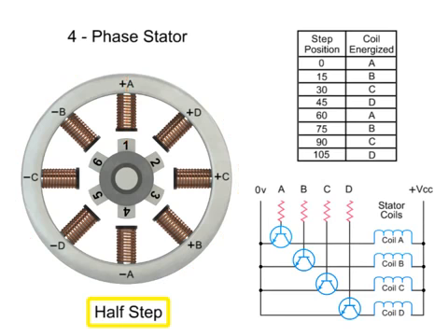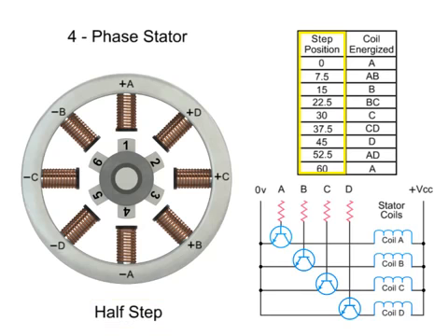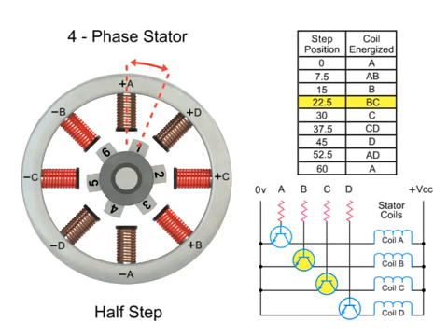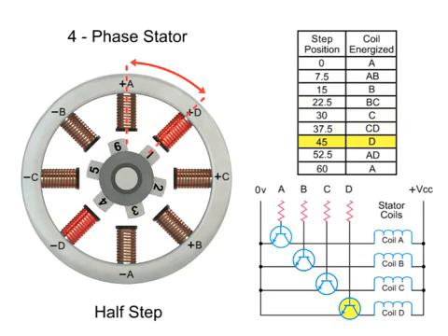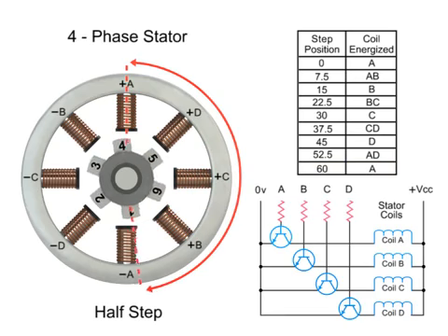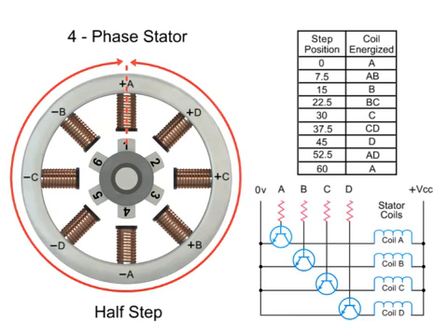For half-step mode, the stepper motor's resolution can be doubled by altering the switching of coils. Half-stepping occurs when one winding is energized and then 2 windings are energized alternately, causing the rotor to rotate at half the distance. Switching coils in this combination will rotate in the reverse direction. As you can see in this example, 48 steps are required to make a full rotation at 7.5-degree increments.